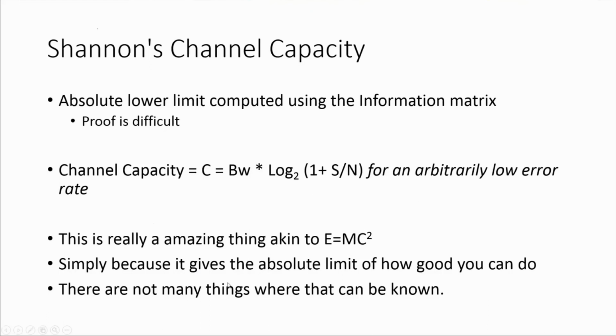What's really awesome about that from an engineering standpoint is no matter what anybody thinks, the channel capacity is the absolute maximum that you can achieve. So there's no reason to try to do better than that. People have got within fractions of a dB of it, but not quite all the way there. Like OFDM using turbo codes can get pretty darn close. So that's another complex topic. One thing I'll make a point of repeatedly throughout this presentation is all those relationships or things you'll read about achieving so many dB within channel capacity, they all include the assumption that you're already synchronized, but they never say that.